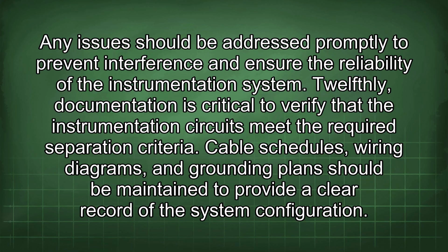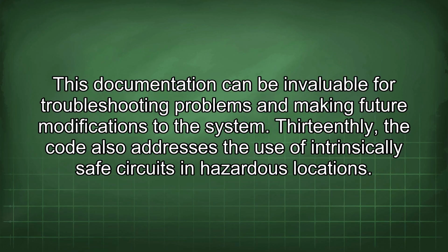12thly, documentation is critical to verify that the instrumentation circuits meet the required separation criteria. Cable schedules, wiring diagrams, and grounding plans should be maintained to provide a clear record of the system configuration. This documentation can be invaluable for troubleshooting problems and making future modifications to the system.